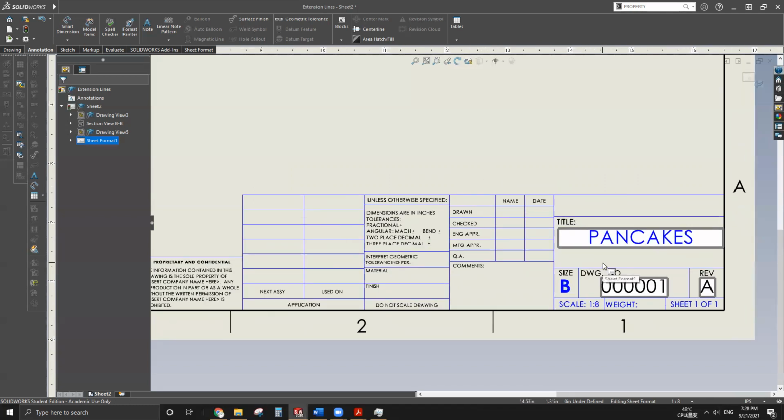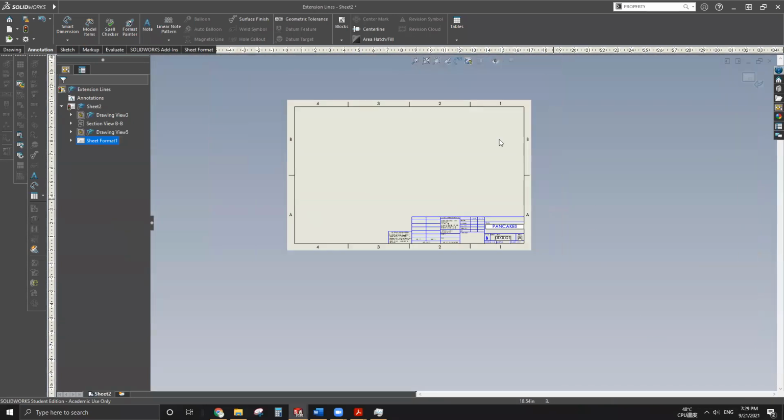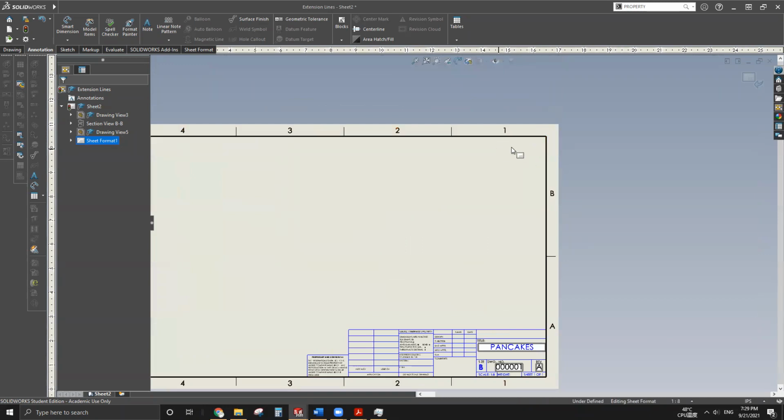Normally, some company just follows the ASTM rules for detail tolerance or whatever, and that's not your responsibility. So title, part number, rev number, scale, your name, your date, material, and finish. That's all I'm asking, okay? And anything you feel necessary, you can make a note right here, like 1, 2, 3, 4, 5, and you can cut out your note from your drawing, or the note just stating whatever you want to say about your part.